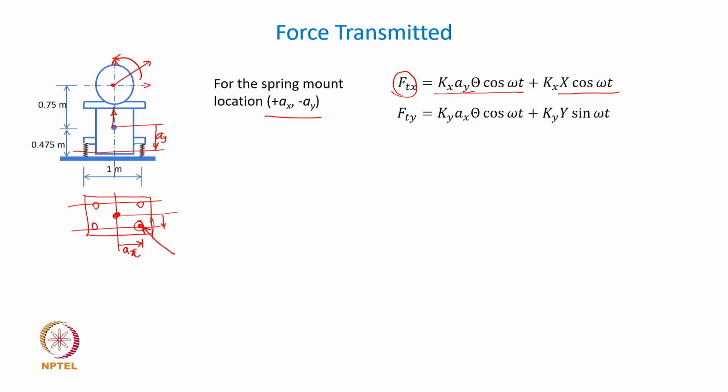So, when the unbalance reaches 90 degrees up, the force along y direction and the movement along y direction will be peaking. So, these relations involving sine and cosine terms should be appropriately used, and the signs here are important, and they will come from the phase relationship between the amplitudes of x and theta. Okay. Y of course is decoupled, it is going to be independent motion.